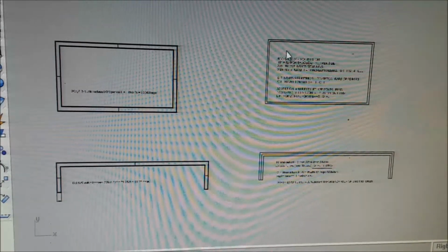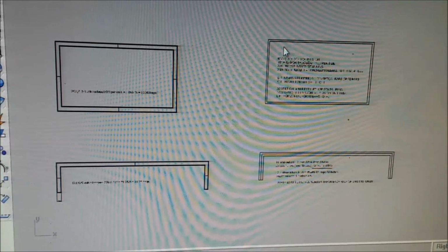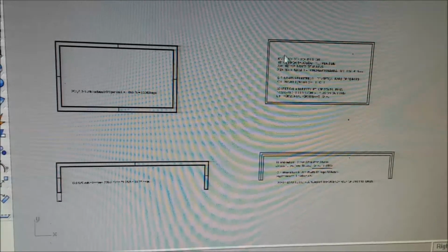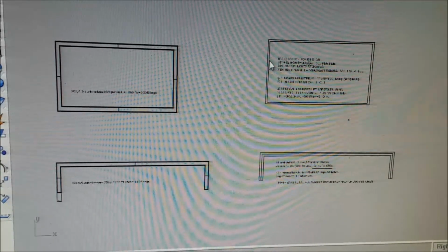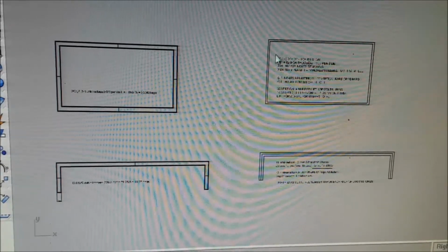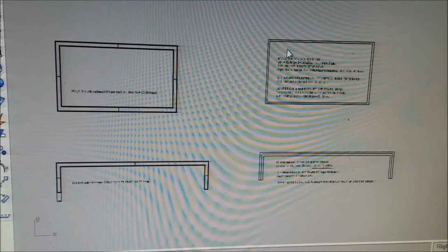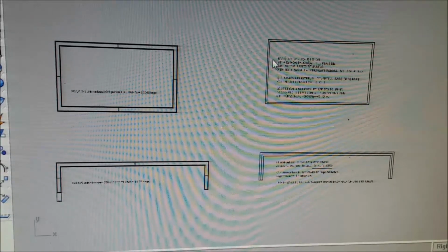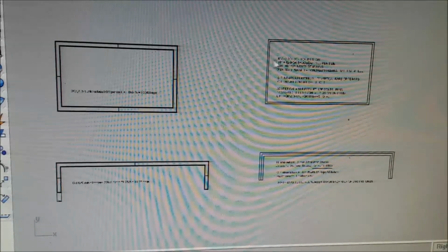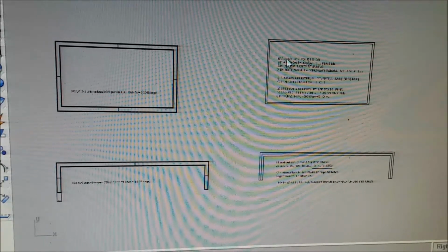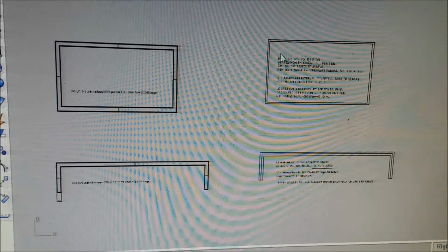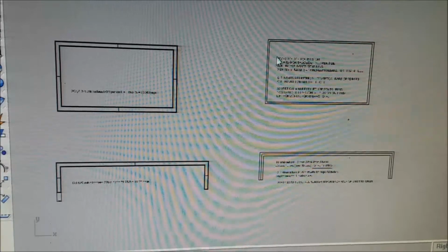The way you get away from that is a bar across the corner, at 45 degrees to your up and down and left and right bars. You take these drops and you put the longest ones right next to the corner, almost exposed, and then you put one or two shorter ones 3 inches behind it, and that reinforces that stress riser right on that corner, and that will keep it from cracking.